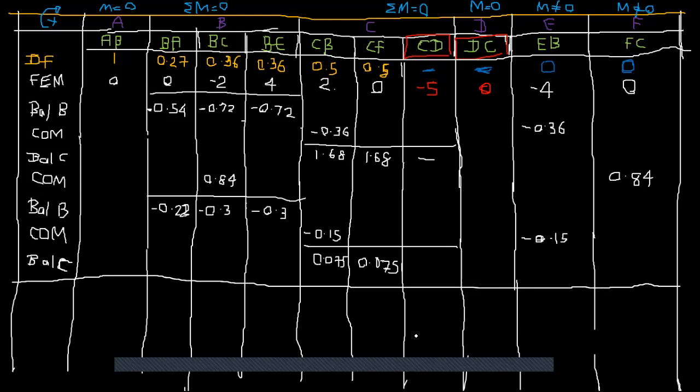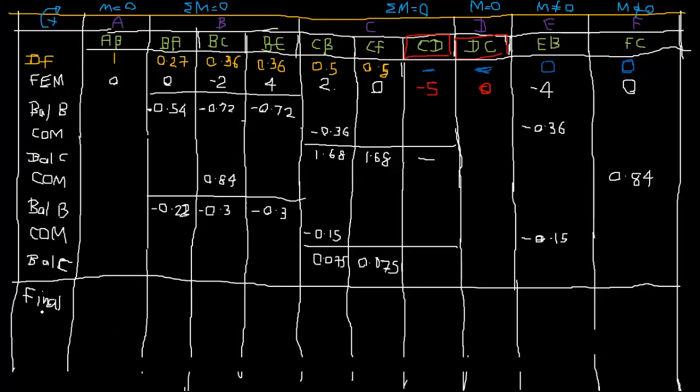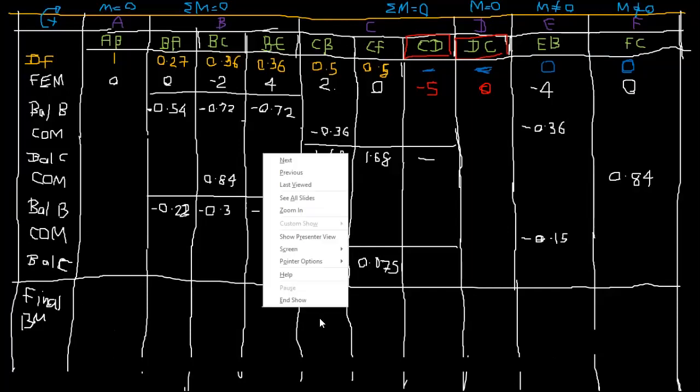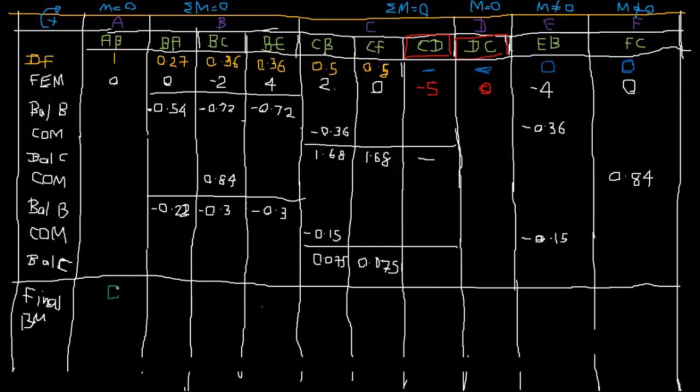Now if you add these values, you will see the final values, the final bending moments. So these are support bending moments, right? So I will write it in another color. So this is anyway 0. So it should be right. That's a discontinuous end and the bending moment is 0. Here also the free end bending moment is 0. Here the value is already solved. It's minus 5.